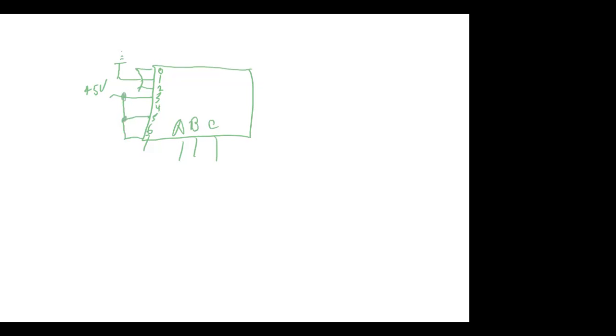And then we'll take D6 and D4 and run them together. That'll need a connection, and that just makes it more clear, I think. So now this is an 8-to-1 multiplexer. Its output is F.